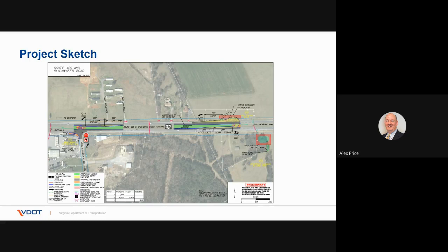The features of the design are clearly shown on the drawing and depicted in the legend. These include where we have full depth pavement, proposed milling and overlay, and removal of existing pavement. It also includes areas of proposed concrete islands, as opposed to leaving these medians as a grass median, or where we're using curb and gutter in the median. It has a proposed drainage concept, including locations of a proposed basin for stormwater management, and all locations are shown for proposed right-of-way and permanent and temporary easements.